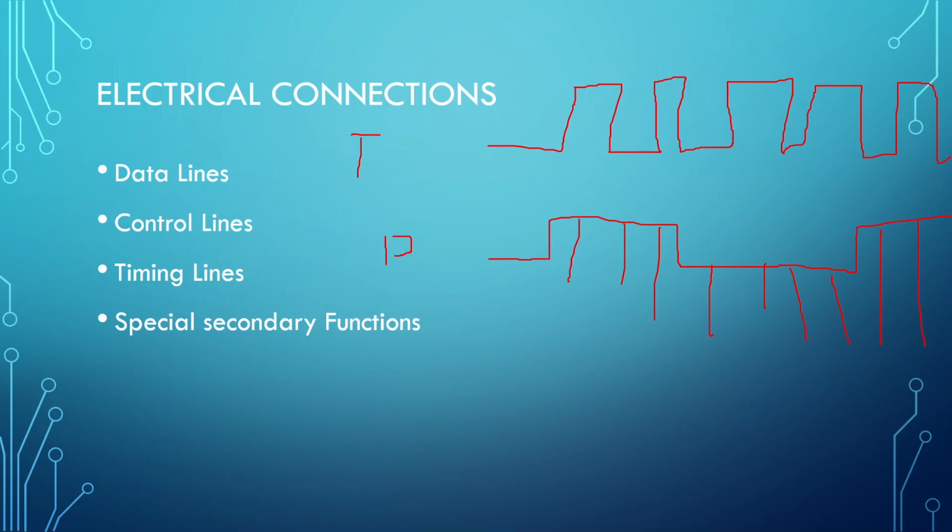Going back here for a second. Hardware handshaking. This is the cause of most interfacing problems, because there's not a perfect standard set. Most of the time when I've dealt with equipment, I've not done synchronous, I've not dealt with handshaking, it's all TTL based, it's just, are you sending data or not? It's simple, 3 wires and I'm done, so I haven't really had this big of a problem, which is nice. Some manufacturers omit the control lines from the RS232 equipment or assign unusual applications to them. So again, lack of consistency.